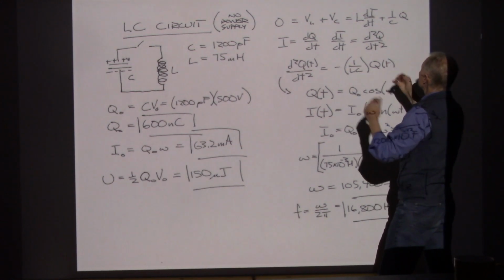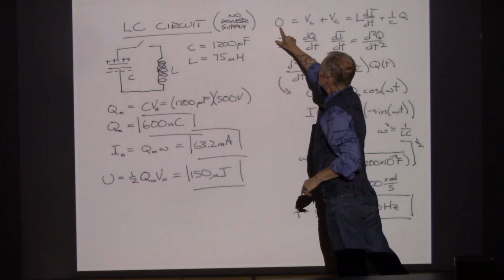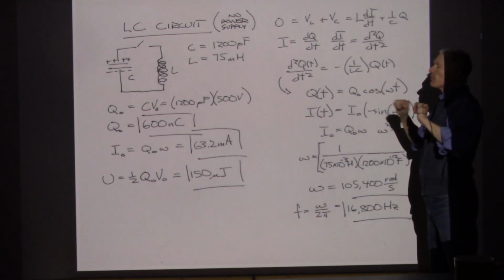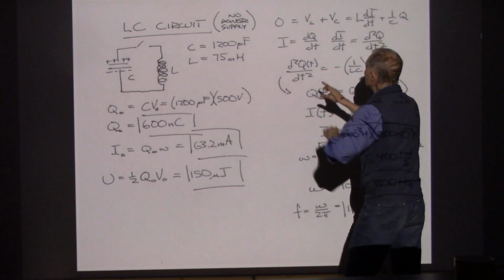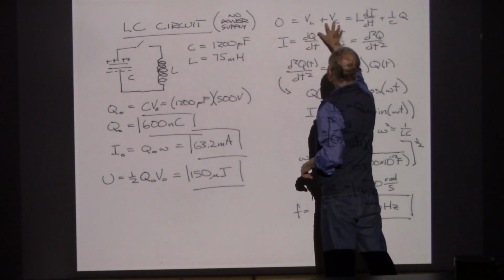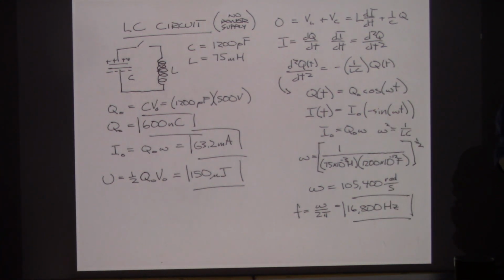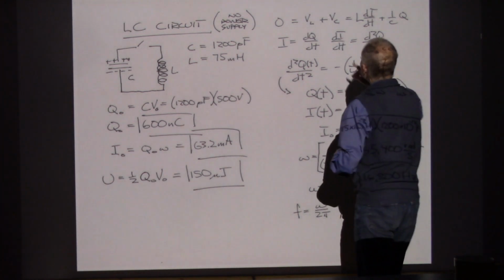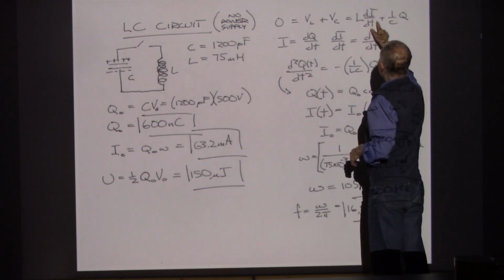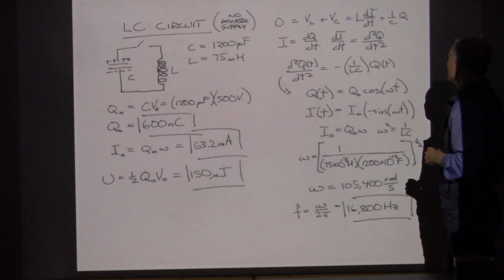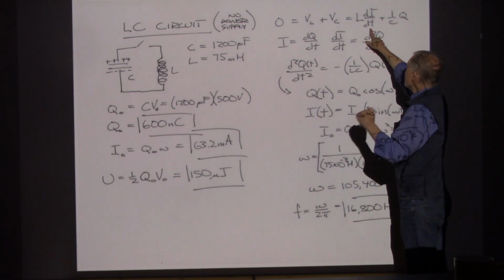Now I could take one more step back and say it's an LC circuit. There are no voltage boosts. There are no batteries. There are no generators. So it's really up to the capacitor and inductor. And in our equations, what we've always done is listed the capacitors and the inductors as voltage drops, not voltage boosts. And so the voltage across an inductor is given by L di/dt. So if you go back to the beginning of the chapter here, you'll see that formula being used to represent the EMF, the back EMF.